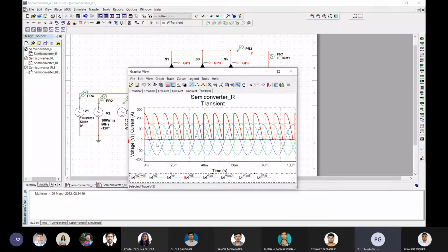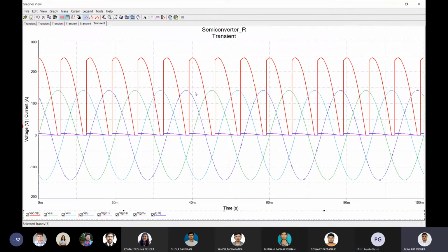For 60 degree the voltage decreases and after that it increases again. But when it is 90 degree, the next thyristor is triggered later, so the voltage decreases till that point. If it is less than or equal to 60, the next thyristor will be turned on before the voltage decreases up to that value. That's why it is coming like this.